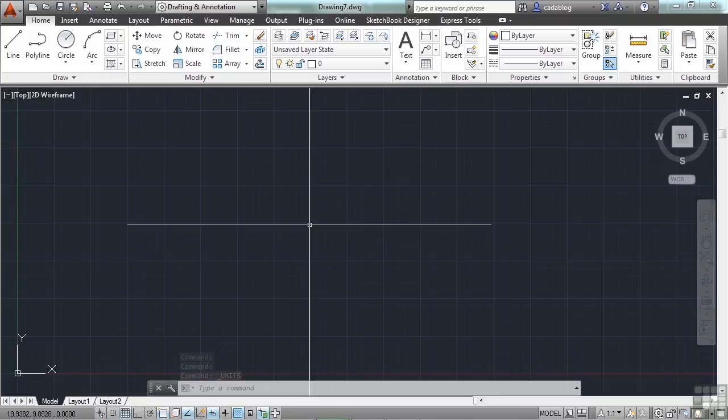It's good CAD practice to draw everything to its real length. That means that if you need to draw a room that is 15 feet wide by 20 feet long, then you draw it 15 feet wide by 20 feet long. Don't scale it, don't guess at it, draw it exactly that. This is good for several reasons. 1, you are always creating an accurate drawing. And 2, your drawing will be properly drawn to scale when printing. And 3, others that need to use your file will know what's going on with your line work.